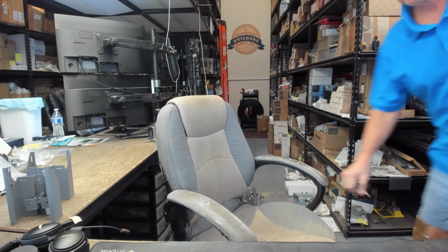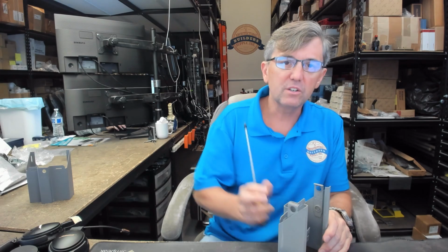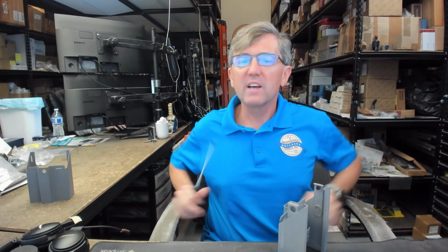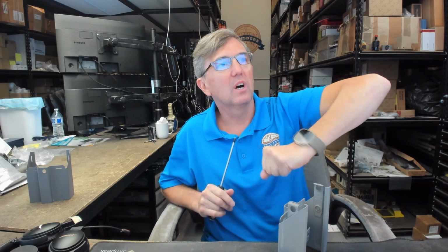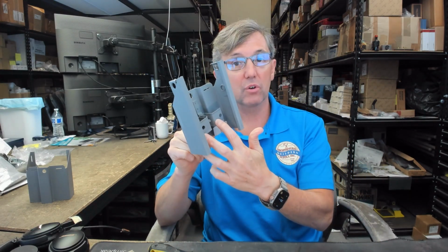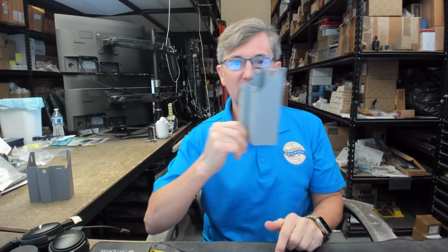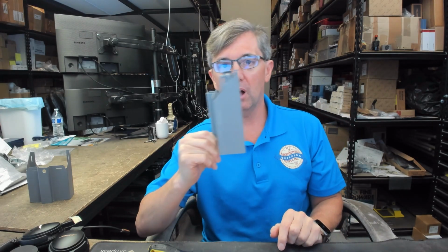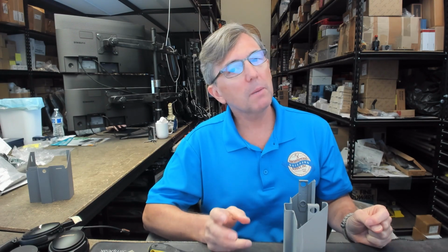You can add compression anchors to masonry frames if for some reason you felt you needed to do that. I've had customers ask me to do that because they were going to take a masonry frame because they wanted the mortar guards or dust boxes, but they were going to put it in knockdown and wanted plumb anchors, which is what these are called as well. They wanted to use these just to help get the frame plumb. Okay, I don't see any problem with that, but I also don't see that being a typical part of installation.